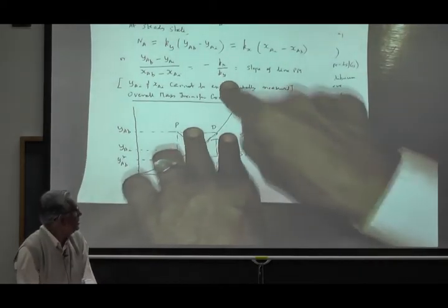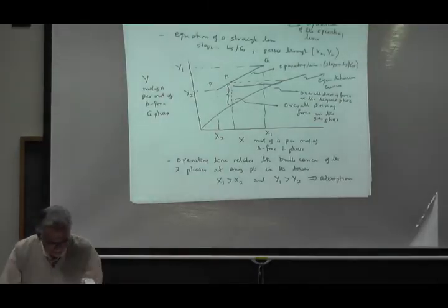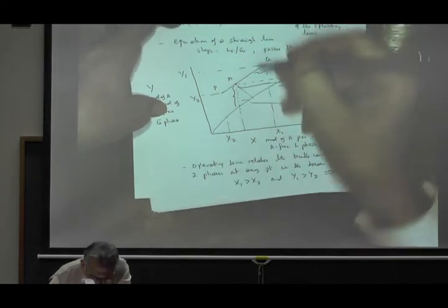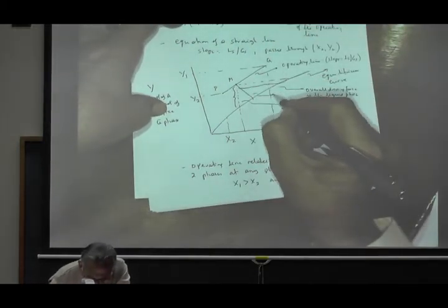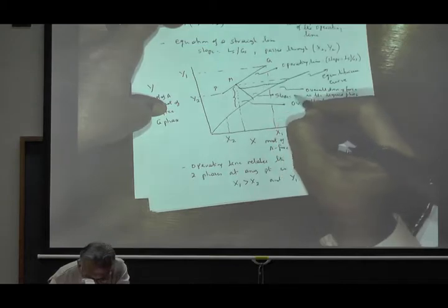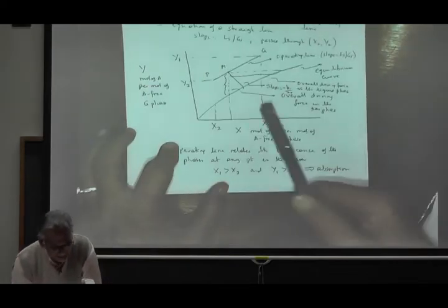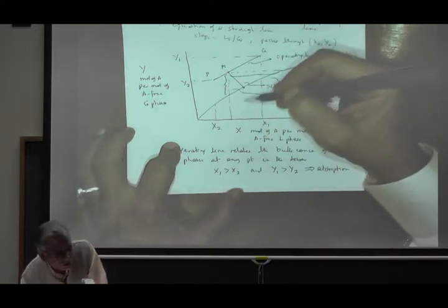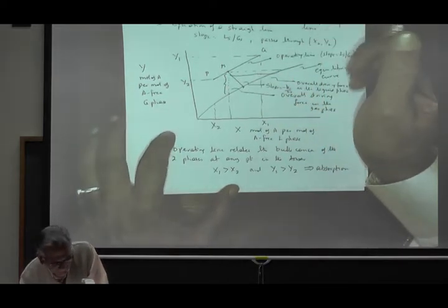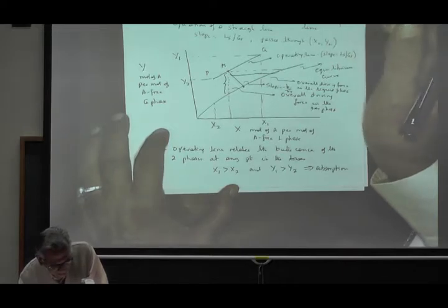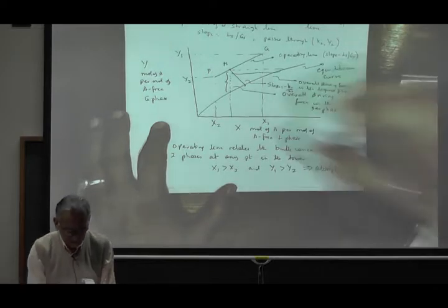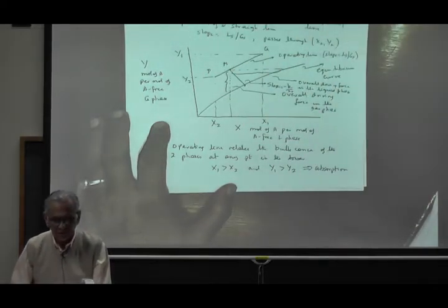Minus kx by ky. So, if you make a line like this of slope minus kx over ky, then corresponding to M, this will give you the interfacial concentration. Any doubts? And this will keep changing. So your driving forces are not constant. They will keep changing along the length of the tower.